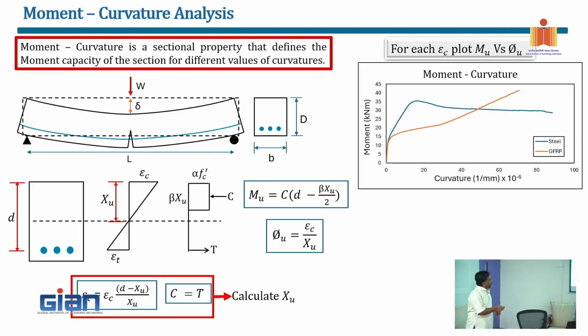So, for a GFRP, if I want to limit the deflection, I have to increase that EI. How would I increase EI? E is the section property. The only way is to increase that I. How do I increase I? I cracked, right? I put more reinforcement, then only the I will go up. Cracked moment of inertia: if I want to increase I cracked, I need to put a lot of steel, a lot of rebars. I should use GFRP rebar.